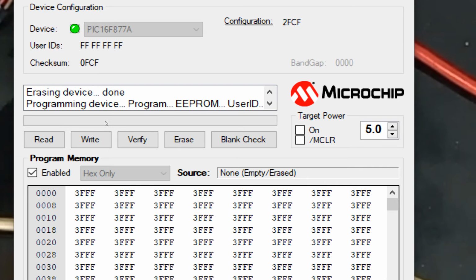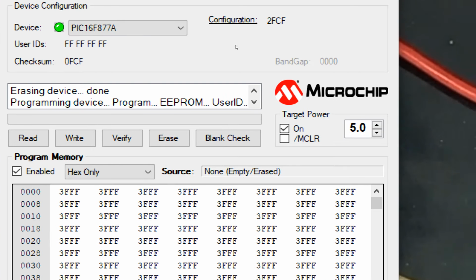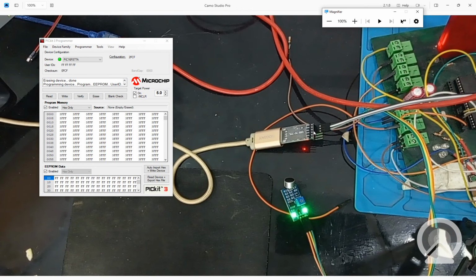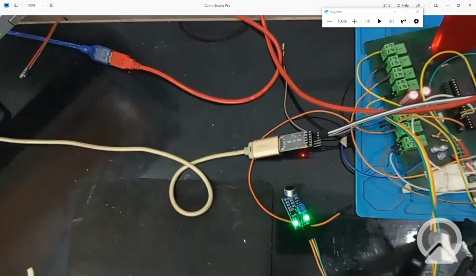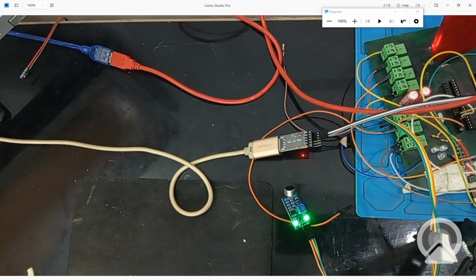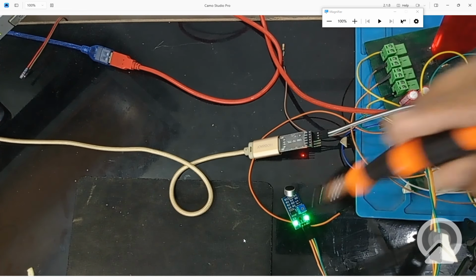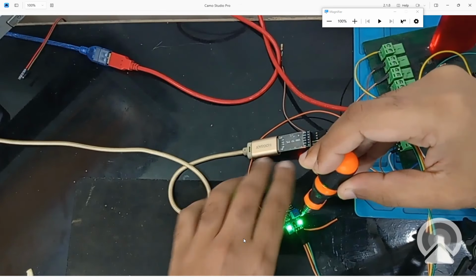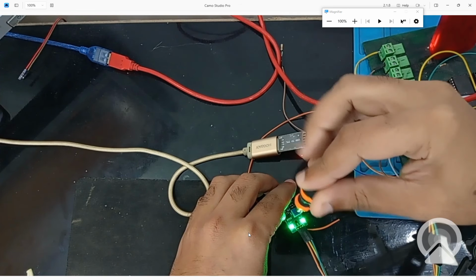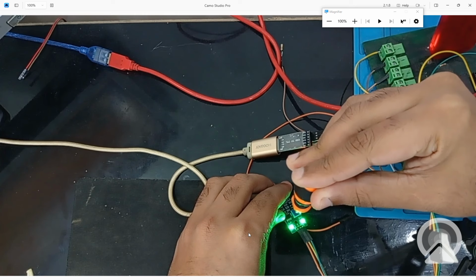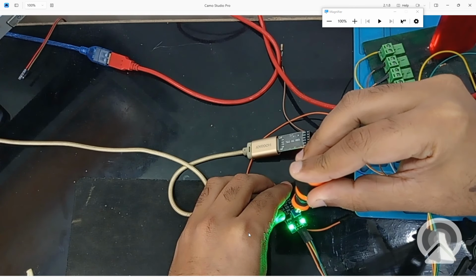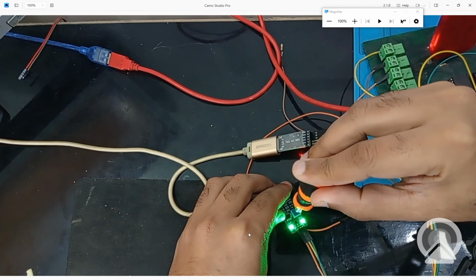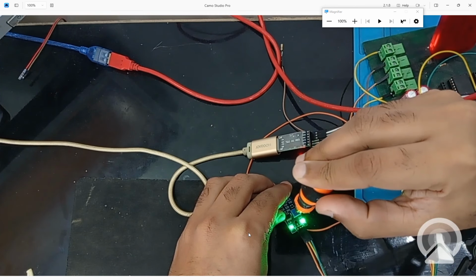So you can simply power up the sensor from a 5-volt source. Okay, now it's powered up. See that both the LEDs are on. Now I use the whistle. Nothing is detected. So we have to calibrate it as per our sound environment. So here you have this potentiometer. You place a screwdriver on it and rotate it. So rotate it in the opposite direction. Rotate. Now see, it has turned off.